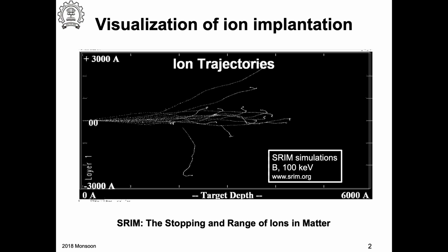If I take, for example, arsenic, singly charged ion and doubly charged ion, and I accelerate them by applying some voltage, then if it is doubly charged, the acceleration would be larger because the mass is the same, but the charge is twice compared to a singly charged ion. If I apply a voltage of, let's say, 200 kilovolts, a singly charged ion would have a kinetic energy of 200 keV, but a doubly charged ion would have 400 keV. As a consequence, the higher energy ions would go deeper into the target material, into the substrate where you want to implant.